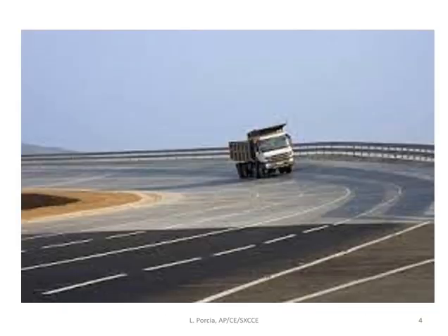In this picture, we can see the outer edge of the pavement is somewhat raised with respect to the inner edge of the pavement. So thus a transverse slope is provided, and this transverse slope is known as super elevation. And this super elevation can counteract the effects of this centrifugal force on a vehicle.